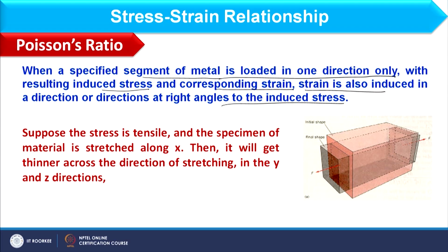You can also understand that through this particular image. This red section is basically the original shape. When I apply tensile stress in x direction, the length in y as well as z direction will decrease. However, the length in x direction will increase. So, though stress is applicable only in one direction, it affects the other two directions also.